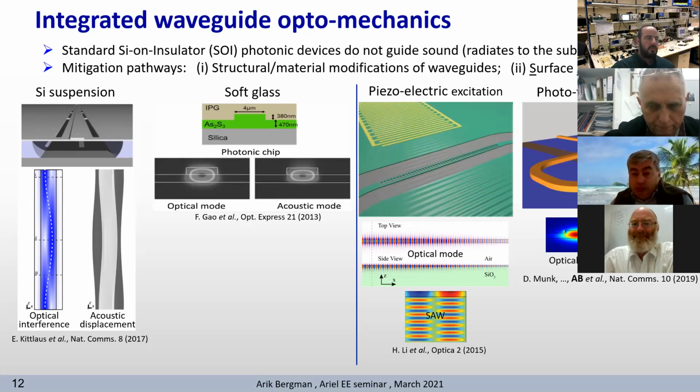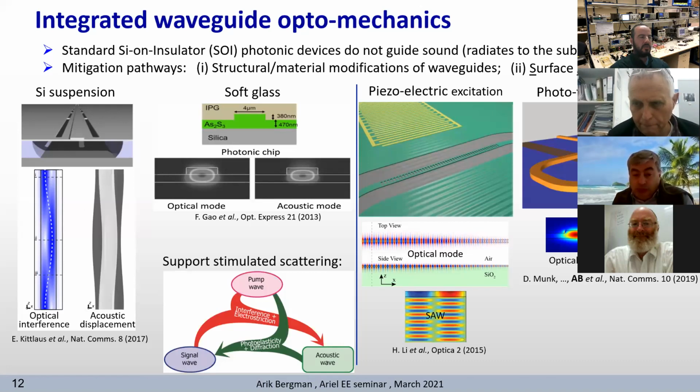One last important note. In both of these SAW devices, the generation of acoustic waves and the optical scattering processes do not spatially overlap. Therefore, the systems on the right lack the positive feedback needed for self-amplification of both the optical and acoustic fields. The systems on the left, on the other hand, do support stimulated Brillouin scattering, similarly to optical fibers.